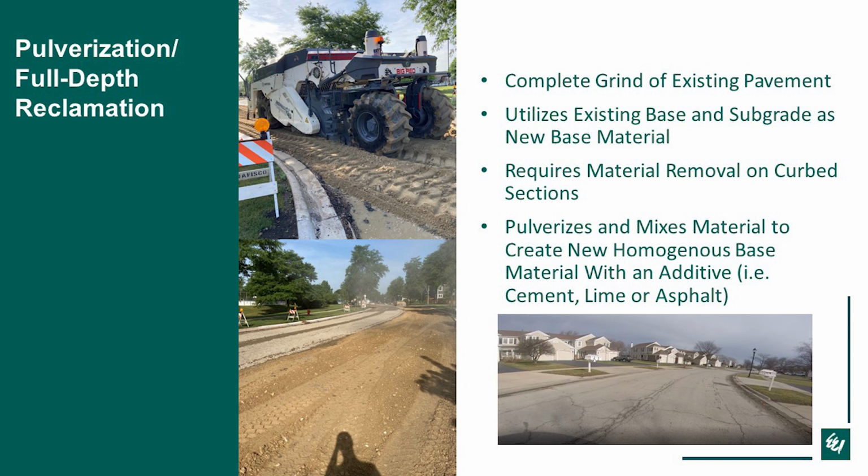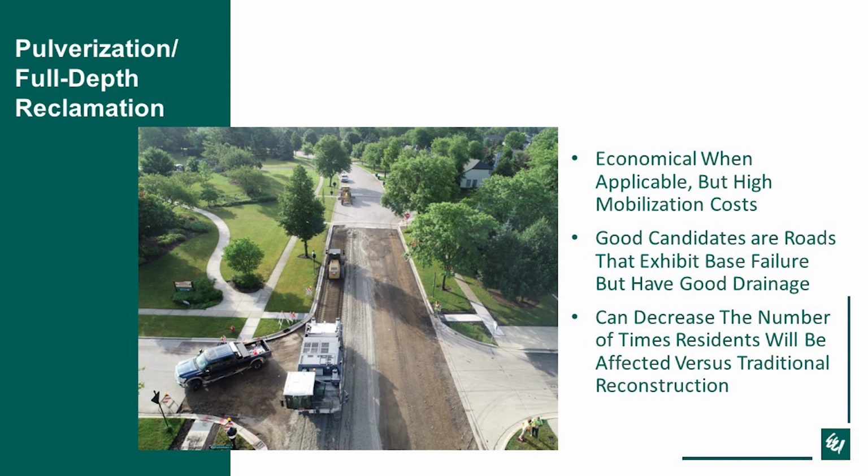This particular project that we utilized it in was an area where the community had existing pozzolanic base and had a lot of issues with freeze-thaw, and we were able to use this full depth reclamation to remediate that and put it back down. It was a little bit more cost effective, but they were also able to get it done a lot quicker. We did the full depth reclamation for this project in 2 days, as opposed to probably 2 or 3 weeks of doing the traditional reconstruct. Couple things to note would just be it's economical when applicable, but there are high mobilization costs.